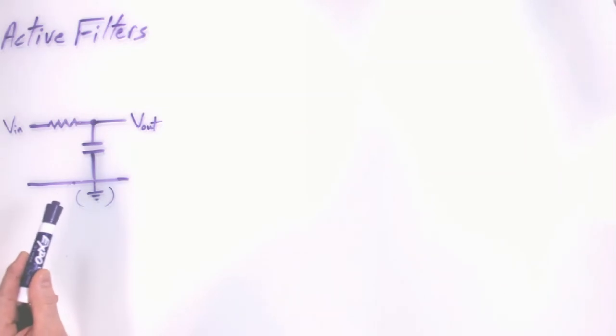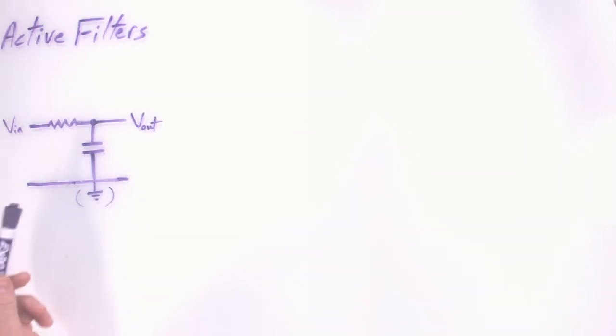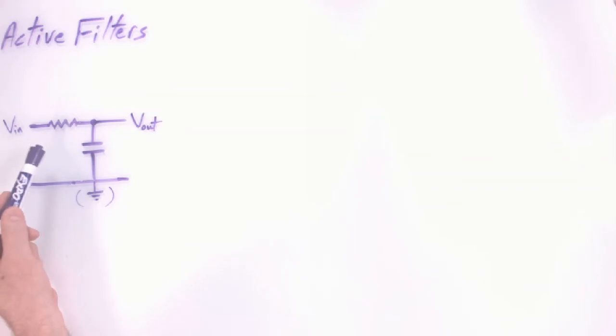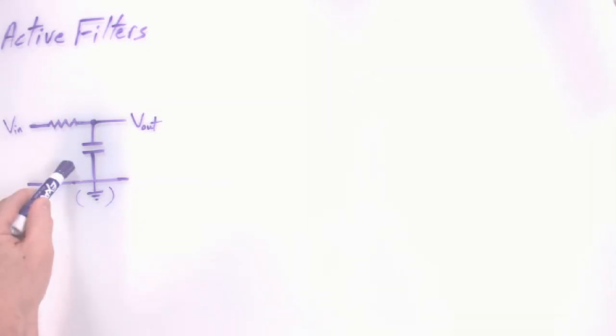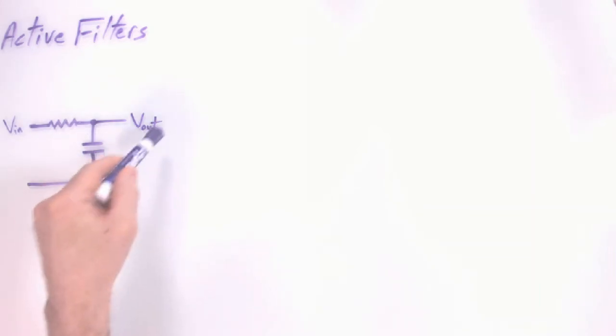And in fact, that is a naming convention for this filter. You could describe it as a single pole, low pass shunt design, because the filtering action is happening by way of a shunt path that the capacitor provides for high frequencies. So they won't get through, they'll get shorted out, the high frequencies will, while low frequencies continue through.